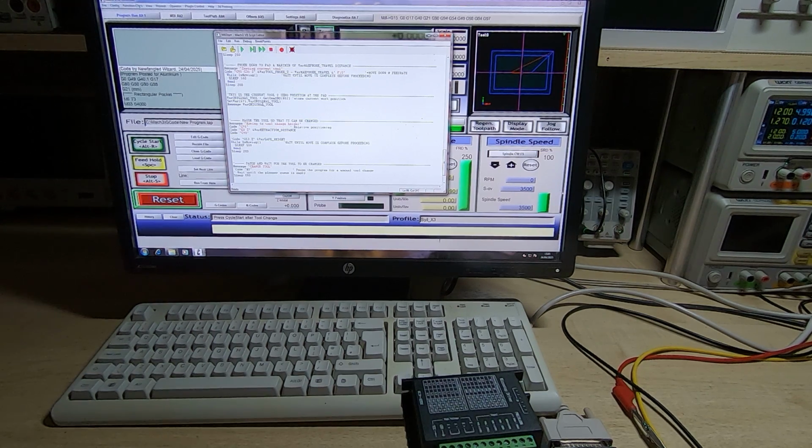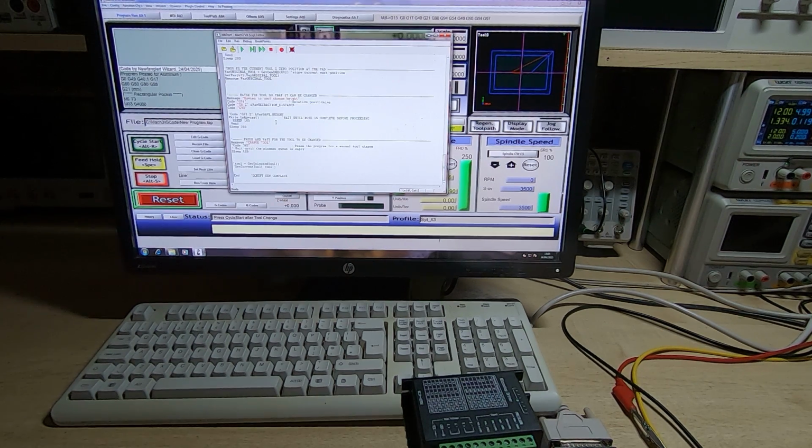It then stops, and we then save that position as our original tool change variable, and we save that as a global variable as well. And we'll also throw a message up on the status line. These messages, by the way, are what appear in this status line. So once it's done that, in other words, we've zeroed the current tool, we haven't changed it yet.